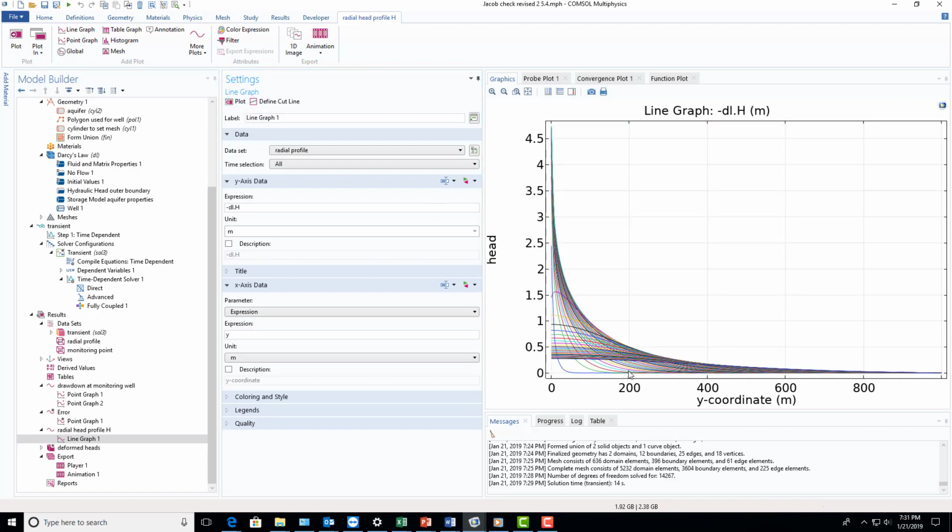Like that. And what you can see is that as the line sink, as the well is active, we have plots, these plots here. So we've got a curve like that that propagates out as the well is active, and then when we shut off the well, the head right here at the well itself drops, and we get this set of curves. Okay, so they're all superimposed.